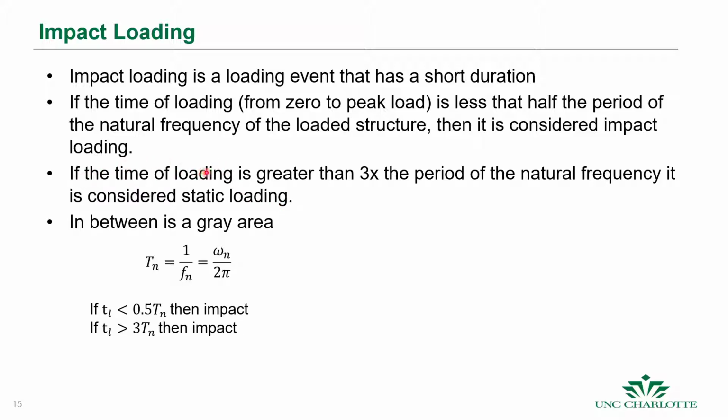If the time of the loading is greater than 3 times the period of the natural frequency, then it's considered static loading, and in between is a gray area. The period of the natural frequency is just 1 over the natural frequency, or in terms of angular frequency, it's 2 pi over omega n. Okay.